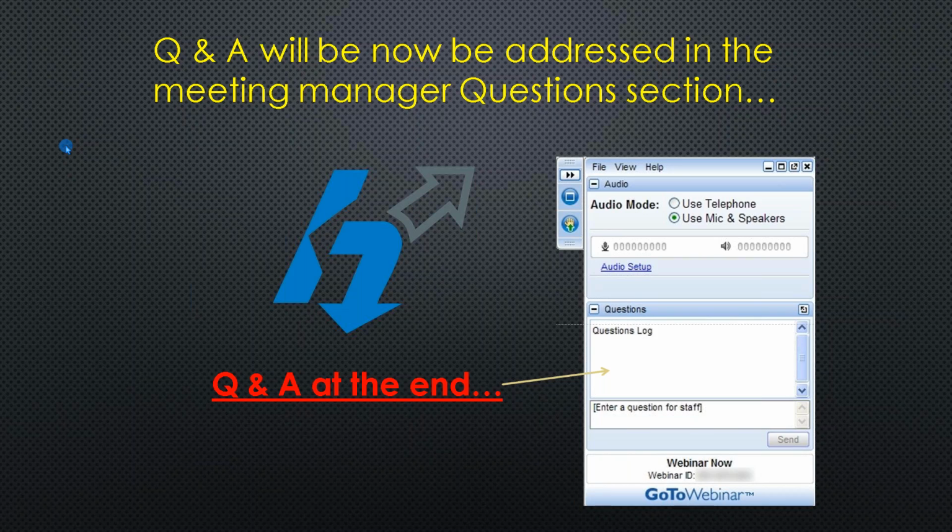Yes, especially for linear static. The report option is not available on all of the Nastran tests, but definitely on linear static and a couple others. You can right-click on that analysis and generate a report, and it will give you material information, boundary conditions, the mesh settings, and then screenshots of each of the result plots. That report you can generate as an HTML or PDF and share inside the company.